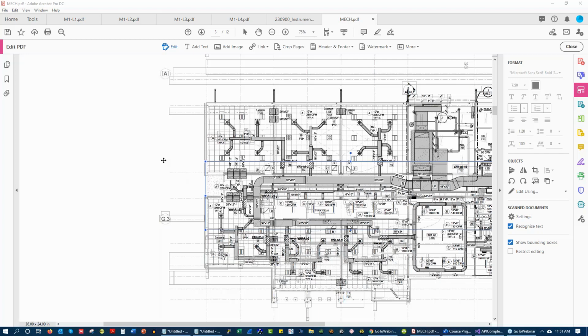So if you have multiple buildings, you definitely should create a BAS standard. You should have standard code. You should have standard graphics. And you don't necessarily have to create it all up front. You should just be asking for this at the end of projects and taking the graphics and the programs that you like the best and using those as your standards going forward.